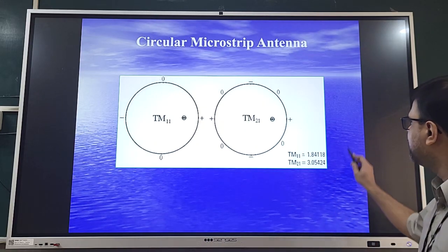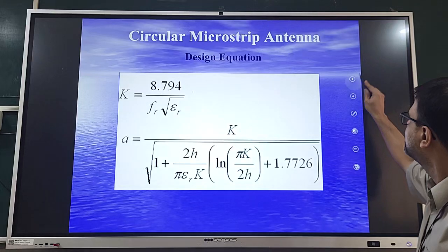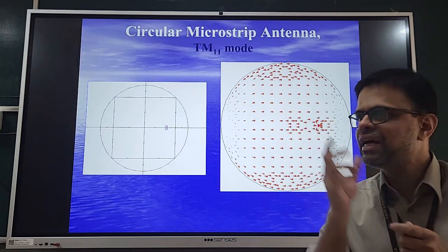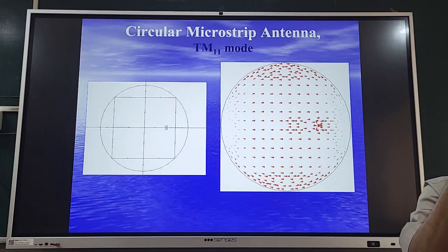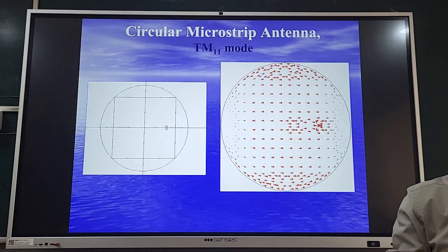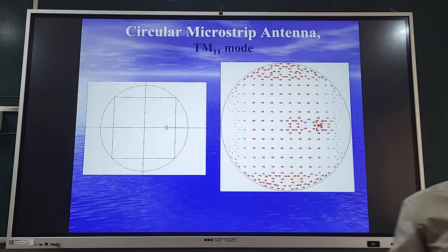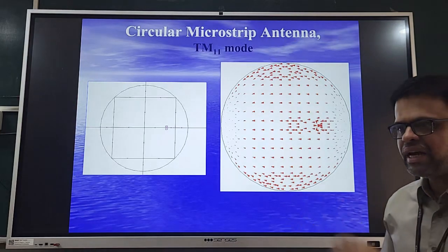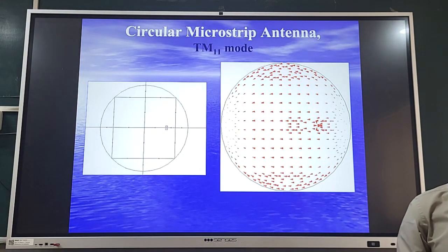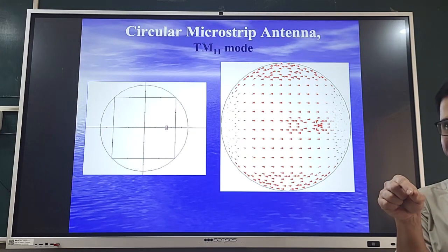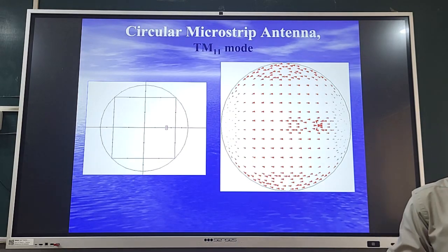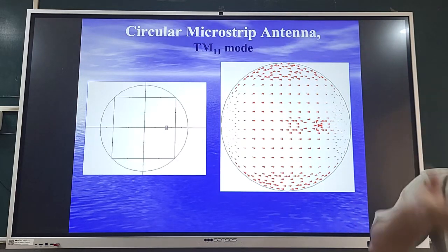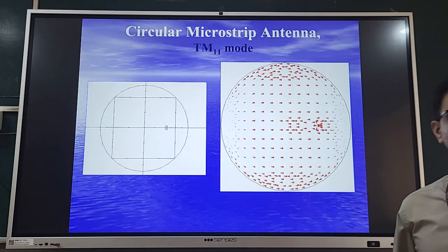A very important advantage of the circular microstrip antenna against the rectangular microstrip antenna is the harmonic separation. Now I will explain that term, what exactly harmonic separation is. What happens is, you design an antenna and feed it from a source. The source is operating at the mode frequency at which you have set it, but inside a source there are frequency multipliers, oscillators or whatever.